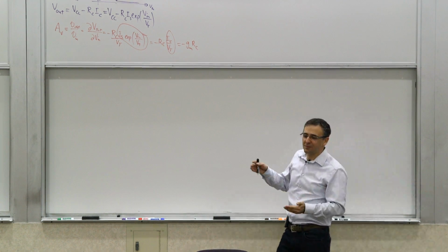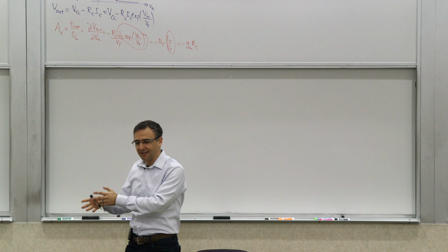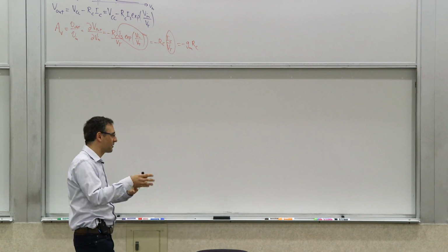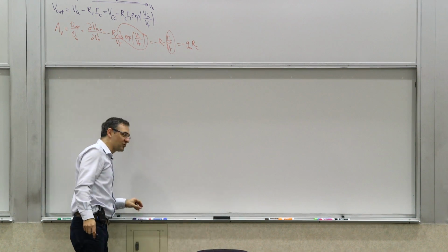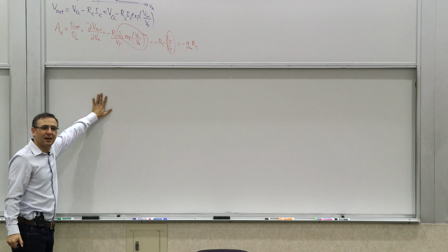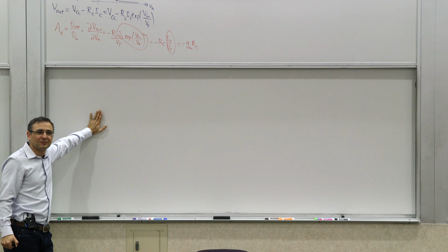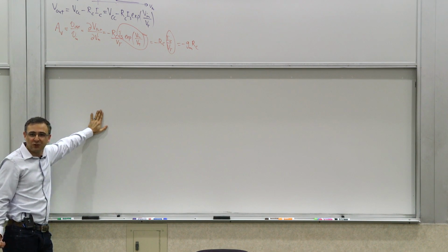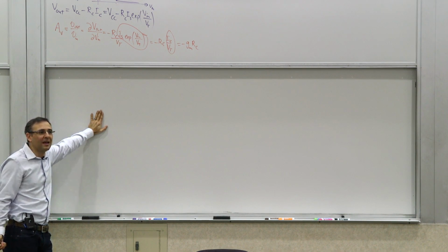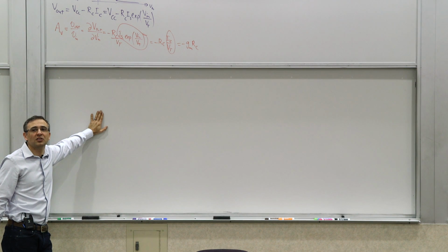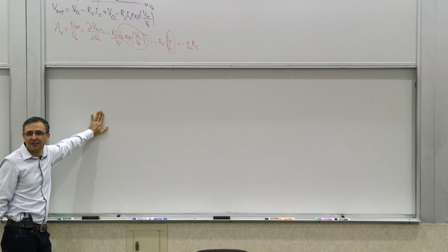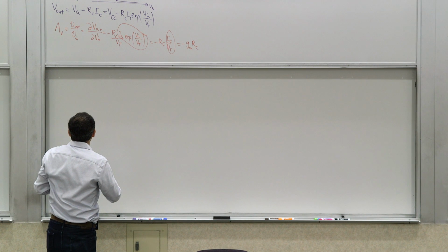We talked about why people initially were doing the T model and then moved to the pi model. There were some historical and probably not completely justifiable reasons. But anyway, this case is actually one of those cases where the emitter is connected to ground. Another terminology for that is that you have a non-degenerate emitter, because when you put a resistor in the emitter, we call it emitter degeneration. That's the terminology that's used. So in this case, we can use the pi model.